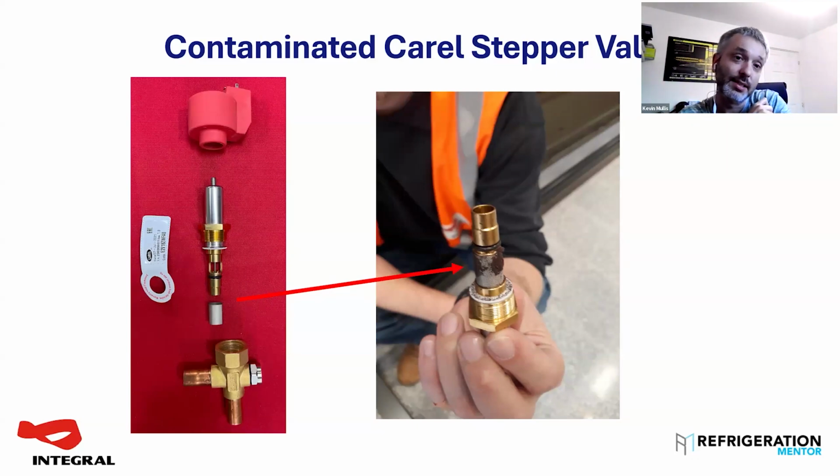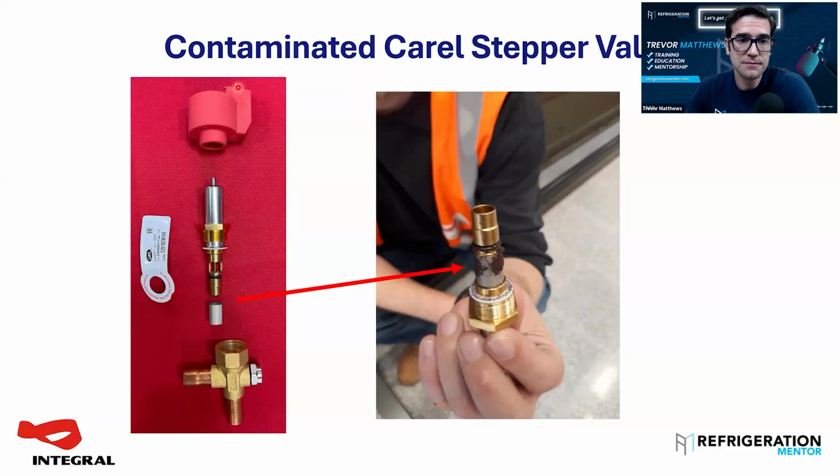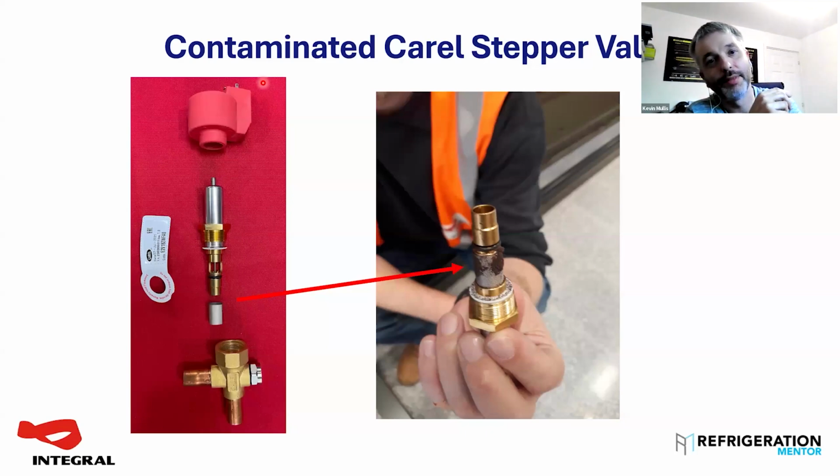Worth saying on these, the older stators, which is photographed there, the plug that plugs in with your expansion valve has to be the right way around. You can fit the plug with a little bit of effort 180 degrees out from where it should be. And if you do that, the valve will drive backwards very handily. So the tail of the cable wants to point towards, you can't unfortunately see it on that photo, but the side has got E2V written on it. The tail of the cable wants to point to the side that says V on it, and that will drive the valve in the right direction. If you've got the cable flipped 180 and it's pointing towards a bit that says E, your valve's going to go backwards, which is not going to be a good look.